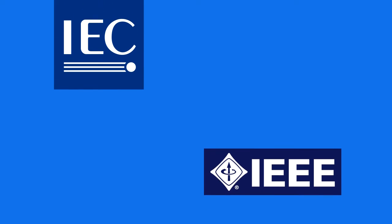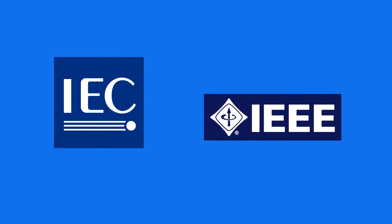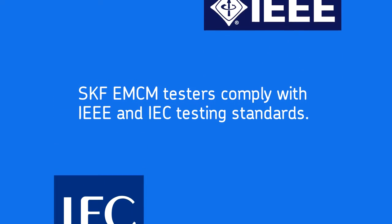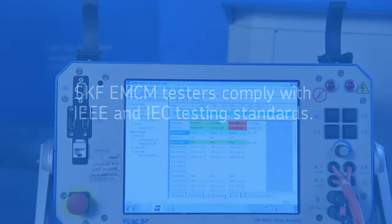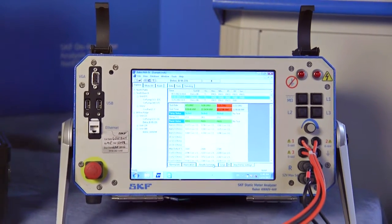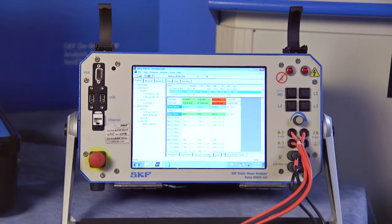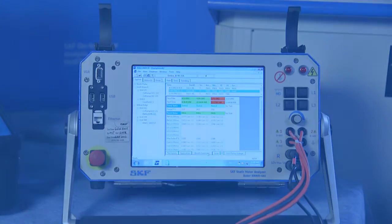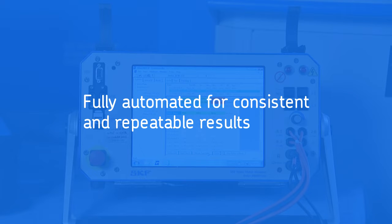Both the IEEE and IEC committees have published standards for testing of motor insulation. SKF EMCM testers comply with these testing standards. SKF offers 2 families of static motor analyzers. The AWA is a fully automated Windows-based analyzer with complete insulation testing capabilities. Since it is automated, you can be assured that the testing is consistent and the results are repeatable, regardless of who is doing the testing.